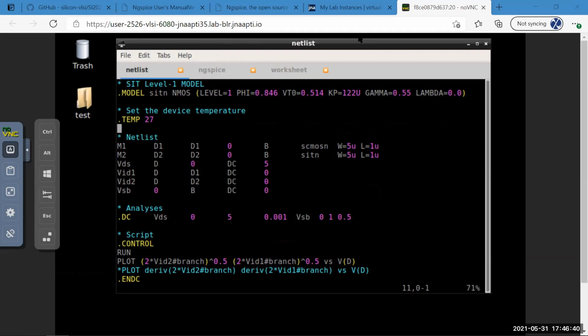Okay, so I think you guys are running something. So Vijayalakshmi, I don't know what you have. Okay, I think I know what you guys are doing. I just got a reply saying that this will only happen if you run out of RAM. And the only reason you'll run out of RAM is if some of the sims, for example, instead of 0.01 you have done 1 nanovolt, or instead of 5, you've done 50 or something like that. So Vijayalakshmi, can you open your netlist and send a snapshot real quickly?